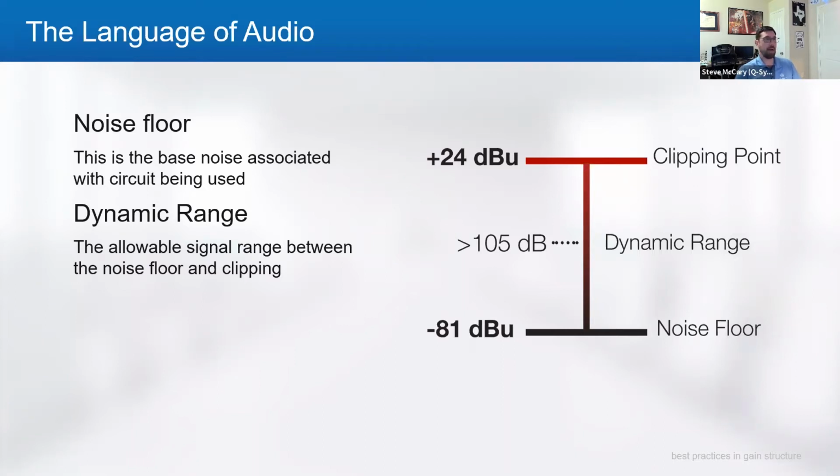And we talk about clipping when, in the dynamic audio class, once your input voltage is higher than the maximum voltage of the power supply, or if the incoming sine wave is larger than the input drive or device can process, then the excess sine wave or the excess voltage gets clipped off the end.